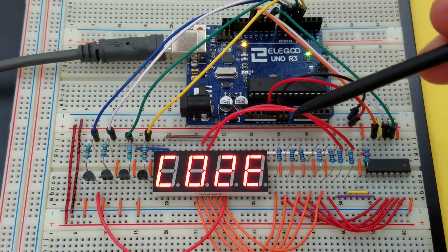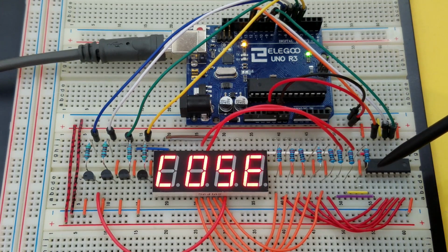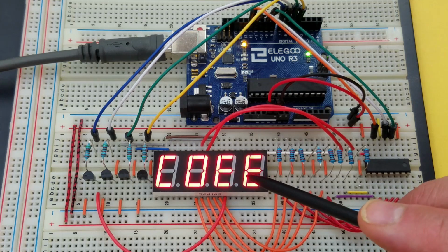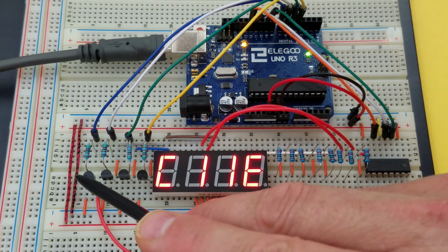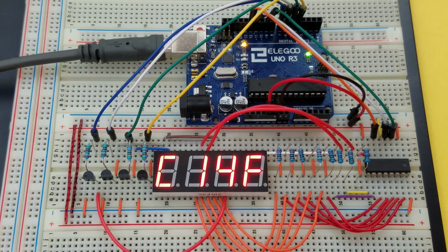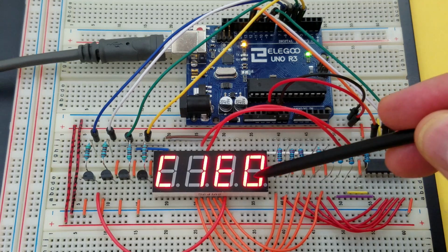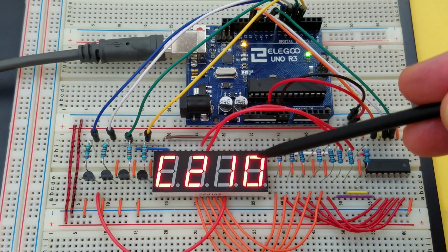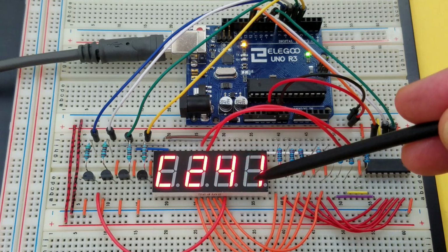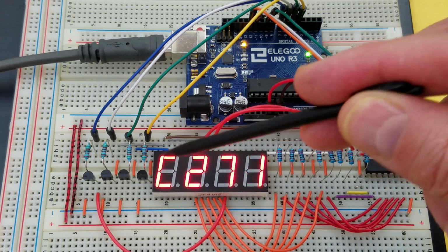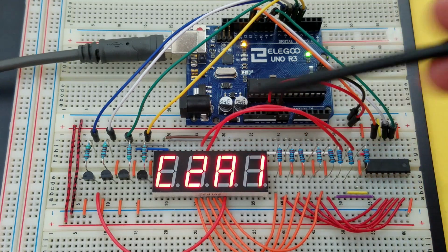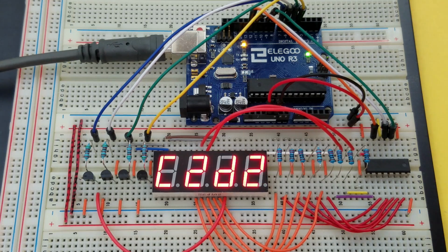All right, so here's the circuit. As you can see on the right-hand side, we have the shift register, and then we have the 8 220 ohm resistors. We have the 4-digit display, and the 4 transistors that will be used to control the common cathodes of each of the digits. Now, like I explained before, this is digit 4, which I'll use as digit 0, the least significant bit. And this is digit 1, which I'll use as digit 3, the most significant bit.